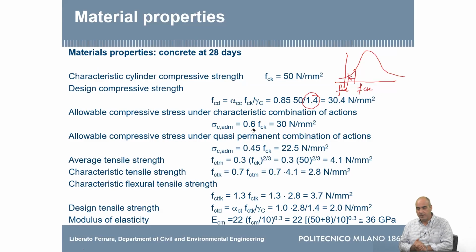And in the codes, you find some formulas or analytical relationships which correlate the tensile strength and the modulus of elasticity of concrete to the compressive strength. That has been the philosophy. You say, okay, when I ask for the performance of concrete, I ask for the compressive strength. You want a concrete, well, I know that here, what is it, C30, C40, something like that.